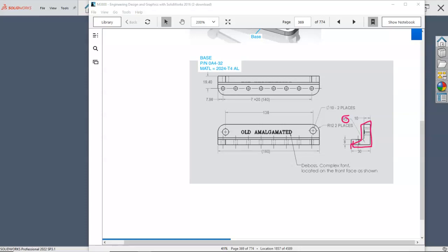And then another technique would be to draw this top and put as much of that geometry in, and then use the contours regions to extrude different parts of sharing that sketch. So I'll do that as a second. And a third way would be to draw it from the front and kind of the same thing. Use that sketch and contours and regions and generate all of our geometry.